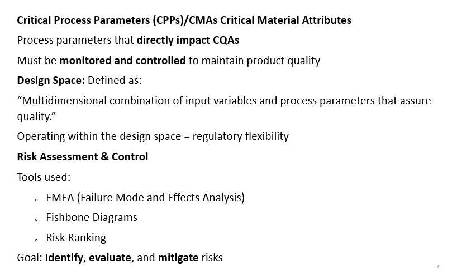In the QbD concept, critical material attributes are required to be studied and defined. Critical material attributes are those material attributes which affect the CQAs. For example, the API or drug substance particle size can impact the dissolution.